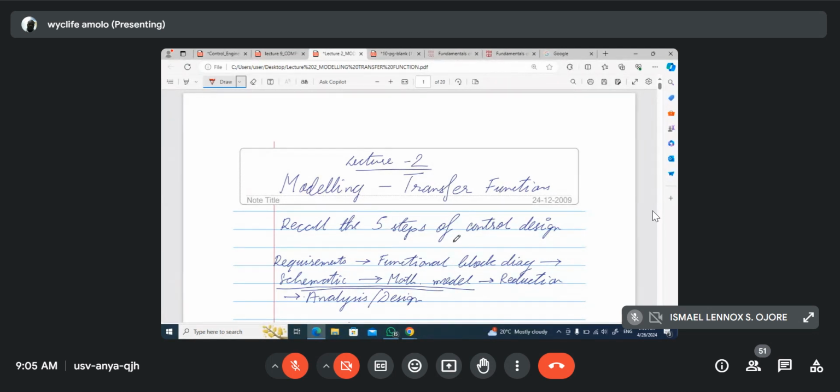So I said that there are three things helping us to have a complete control based on the PID. Just like you put it, P is the present, integral is the past, and derivative is the future. There are certain things that we need to minimize because you don't want to override the system away from the requirements, because if you do, you generate more error.